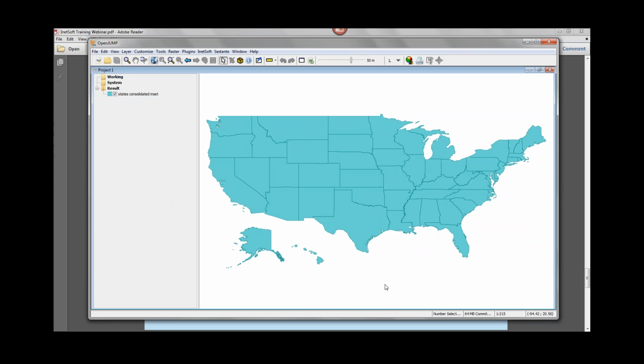Okay, now the next set of steps that we're going to do before we export this is basically targeted at reducing the size of the exported map, right? Because there are various things that we can do that will reduce the size. For example, reducing the number of polygons, reducing the number of node points, reducing the precision with which numbers are represented. So all these steps are optional, but generally you will want to do them because file size can become an issue with some of these maps that have very complex boundaries and so on.